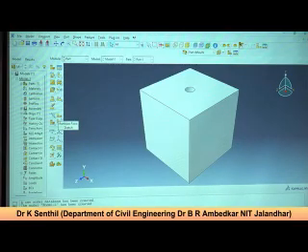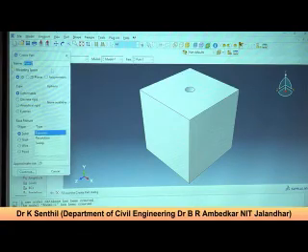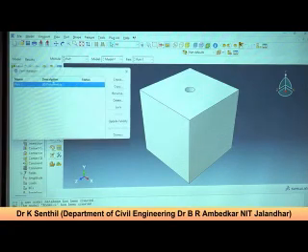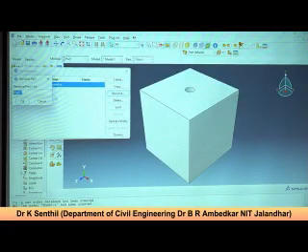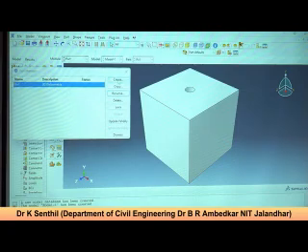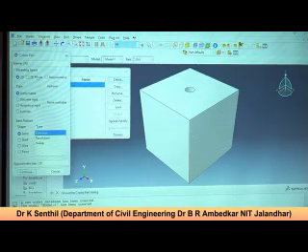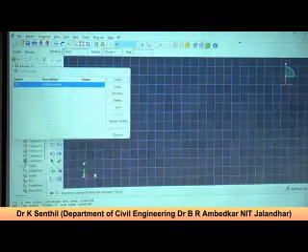Now you have to create the pile so that you can insert your pile later. So now let's go to this create part. Now you can rename this. We have the name Part 1. Rename it as soil. Now create pile. Same deformable, solid, extrusion. Continue.